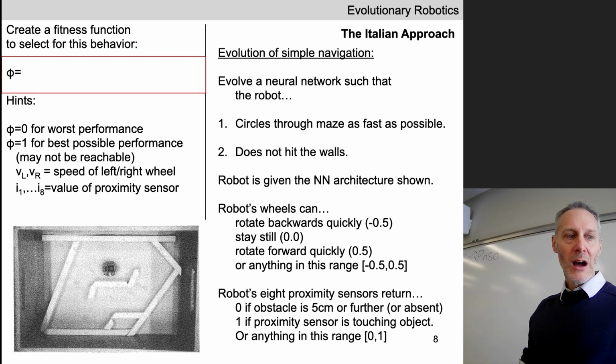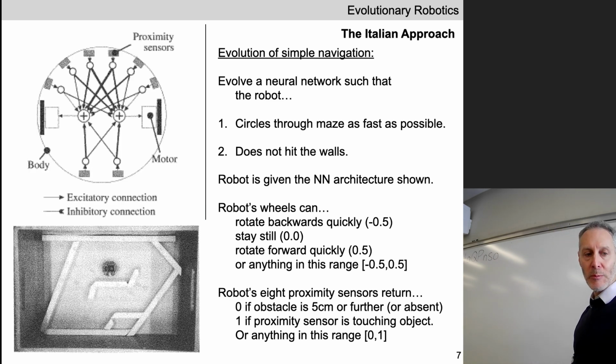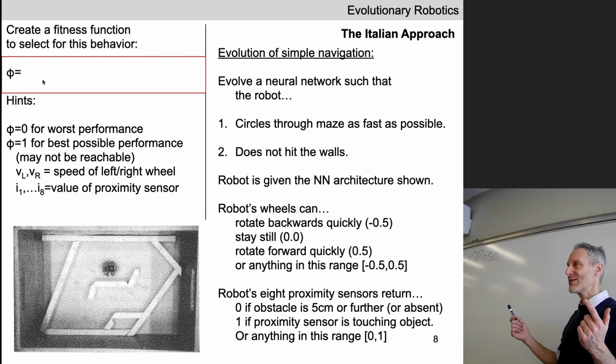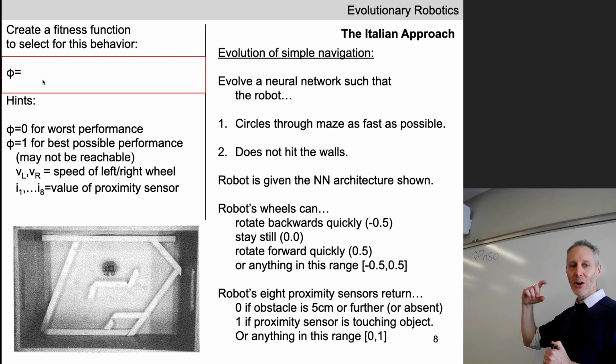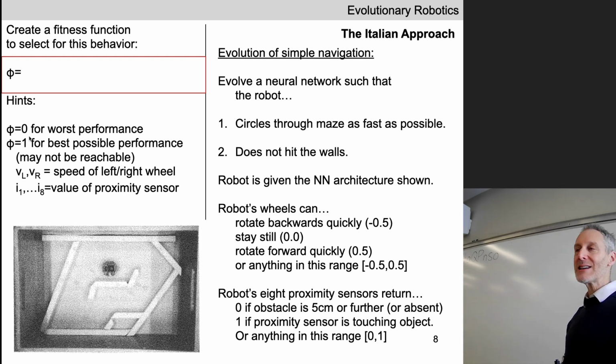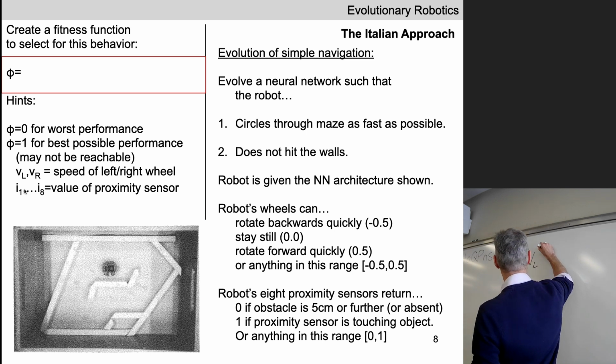Okay, so let's assume for the purposes of science here, we want to see what kind of behaviors we get. Let's assume we do throw into this fitness function the absolute value of VL plus VR. So we know the kinds of things we're going to get, but some of those solutions are go forward, crash into the wall, go backwards, crash into the wall. That's a necessary condition, but not sufficient. We've got to incorporate the infrared sensors in there also so that it doesn't crash into the wall. How might we do that? We've got this so far.